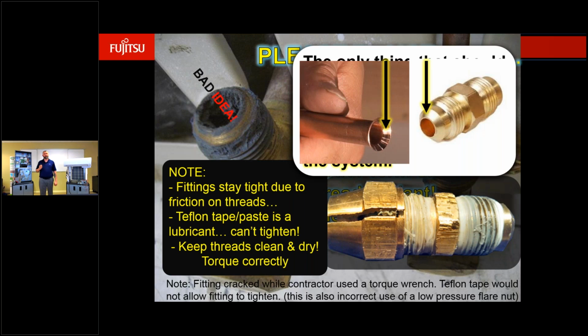The flaring tool that you're using is also going to be very important. The one that I recommend using is going to be orbiting and popping. Basically what that means is on the inside of the flare tool itself, the head will actually oscillate and move around the fitting, as opposed to an old flare block that just pushed the copper and formed it.